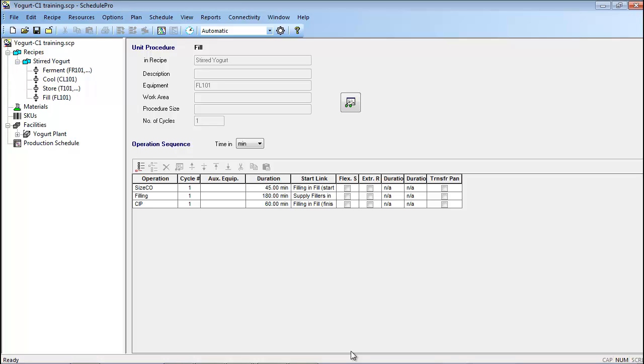Another change related to the filling operation should now be made to the structure of the recipe. In the original plain yogurt recipe, we assumed that all procedures in the recipe would handle the same amount of material, which was equal to the recipe batch size. With the introduction of flavoring, this is no longer the case. Now, 10% of the final yogurt amount is attributed to the flavoring added at filling time, which means the remaining 90% is milk.